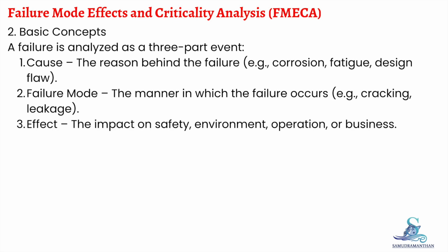Basic concepts of FMECA. In FMECA, every failure is analyzed as a three-part event. First one is cause, the reason behind the failure, such as corrosion, fatigue, or a design flaw. Second, failure mode, the manner in which the failure occurs, for example, cracking, leakage, or overheating. Third is effect, the impact that failure has on safety, the environment, or the operation and business performance.